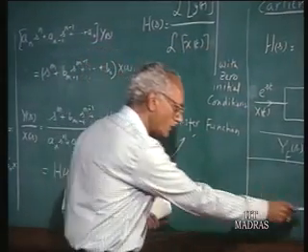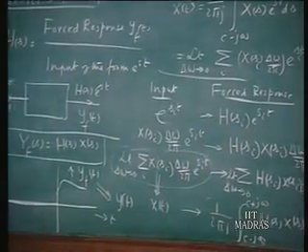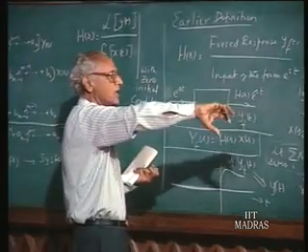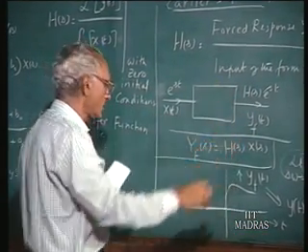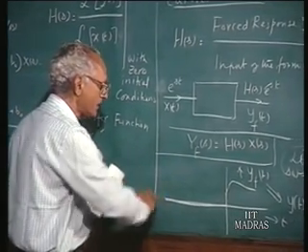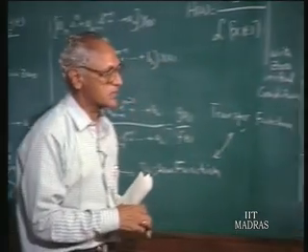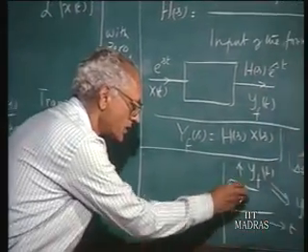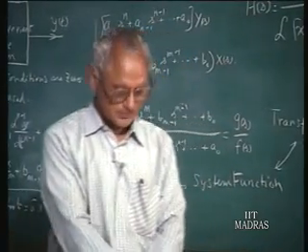The reason we call this the forced response is that all these tiny exponentials start from minus infinity onwards. All these exponentials are starting from minus infinity, and each of them produces a forced response, and the sum of those forced responses agrees with the total solution for negative values of time. That means there cannot be any other additional terms starting from t equals minus infinity onwards. But yf(t), as far as this part of the solution is concerned, includes both the transient and steady state terms, which we talk about in a conventional fashion.